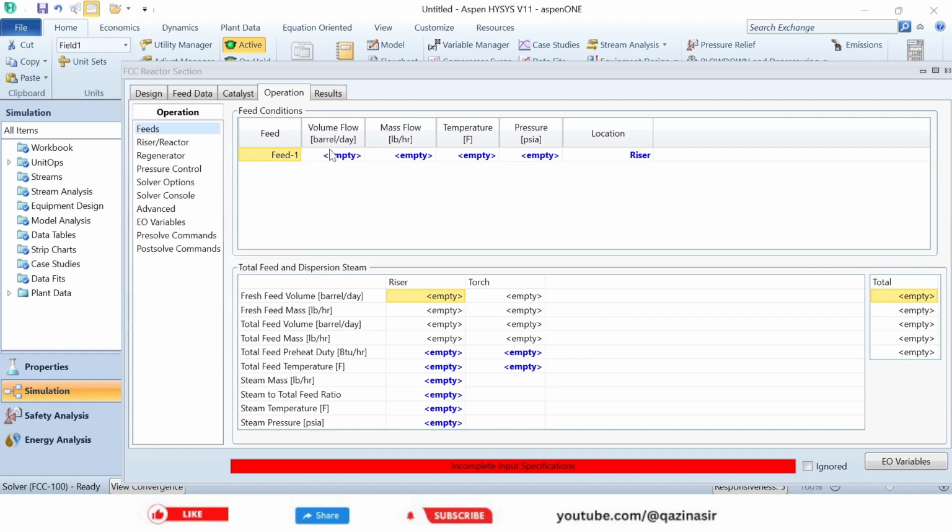After providing this information, we can move to the operation section of the FCC reactor. Here we need to provide the information for the feed, which is volume flow in barrels per day. The value is 37738.8. Again, these values are provided in the Excel sheet. Please download the Excel sheet and you can access all these values there. The temperature is 347 Fahrenheit. Pressure is 43.51 pounds per square inch.